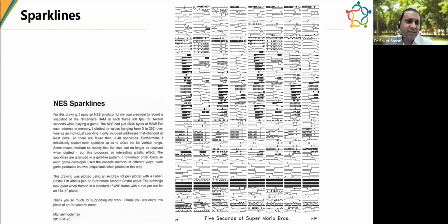Other way is called Sparklines, okay? And where you can actually plot, say, hundreds or 500 or 1,000 of time series on a single graph, right? And again, this is very useful if you're looking at very finely looking at things happening in different spaces in the building or across different variables to say, is there an anomaly? Is my software behaving right? Are there some spikes somewhere? Is there a constant simultaneous cooling, heating? Is there a window left open, right? So any abnormal behavior in any of the variables, you can just plot everything together and then see what is different, right?